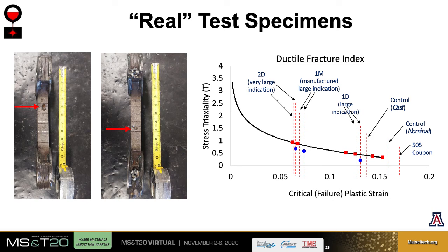Apparently, there was a shift in the pattern when the casting was poured, which caused that thickness to be smaller than intended. The indication did not reduce the cross section enough to make it smaller than the area where it actually failed. The ductility dropped as the indications became larger in the tensile specimens that we tested. However, measured tensile strength did not show a clear trend with indications.